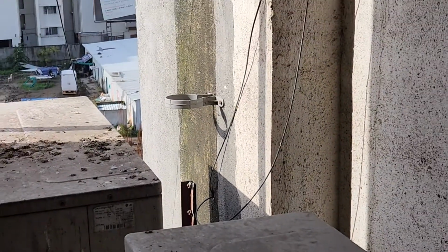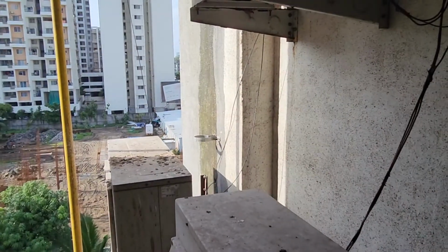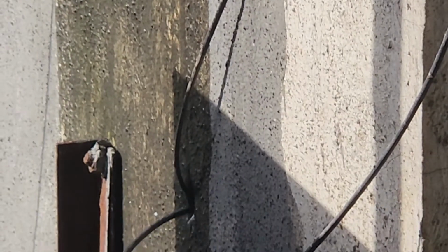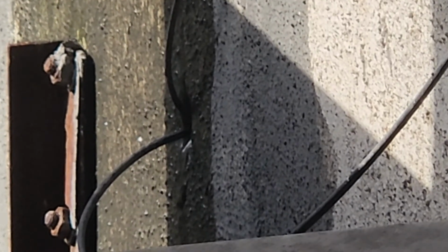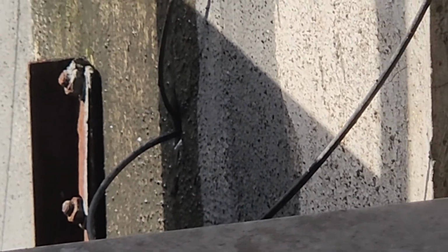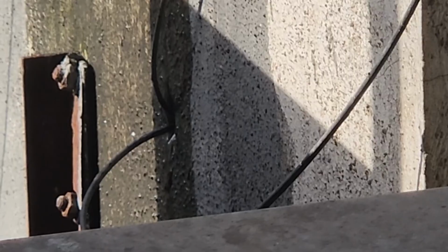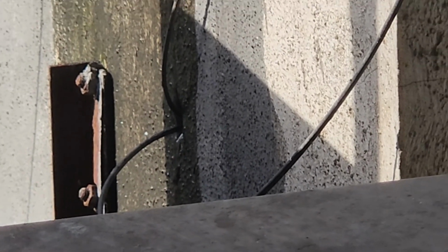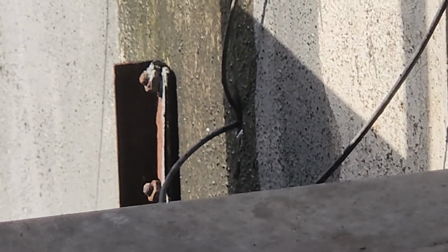If you just put a scale or something like that, you will notice that from there we are noticing the leakage. So we notice the leakage source is the hole which they made for the Wi-Fi cables. The water is coming from the building upside down, you can see clearly the water seepage is there, and it is entering the inside of the building through that hole. So we identify this is the cause of the leakage.